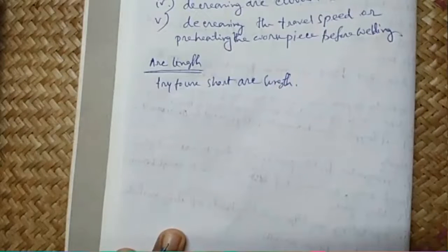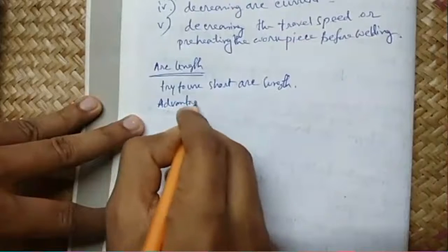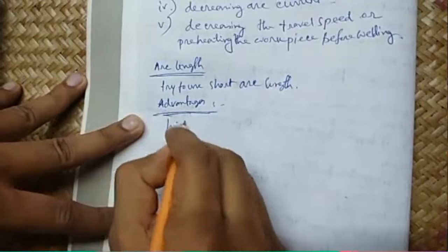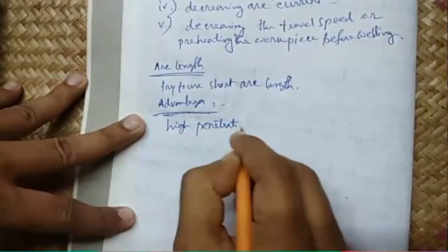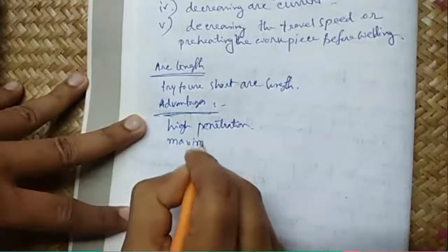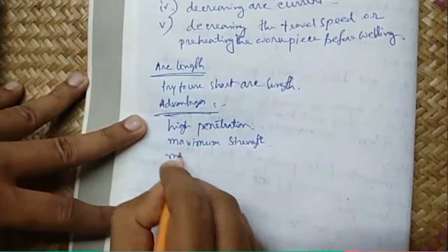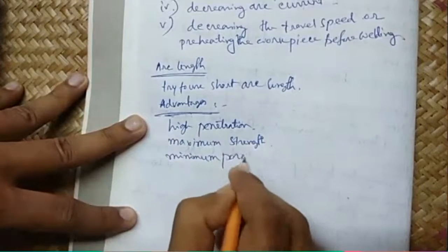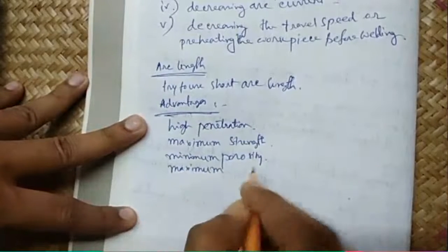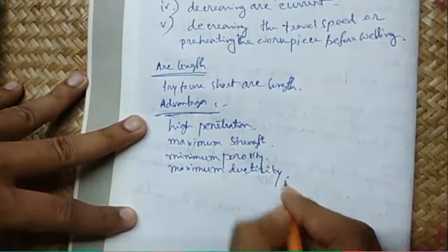And that will give you advantages like high penetration, maximum strength of the arc, minimum porosity in the weld, and maximum ductility in the joint in the heat-affected area.